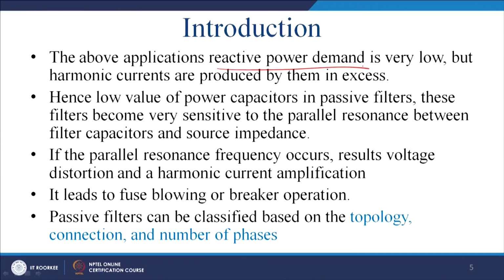And why is this problem complicated? In the above applications, the reactive power demand is quite low, but the harmonic currents produced by them are quite excessive. Fifth harmonic will be the dominating one, and it has a huge amount of fifth harmonic. Hence, with a low value of power capacitor in passive filters, these filters become sensitive to the parallel resonance between the filter capacitor and the source impedance.